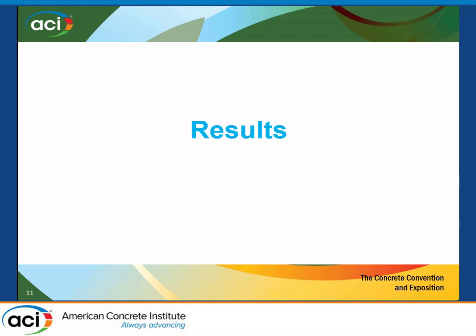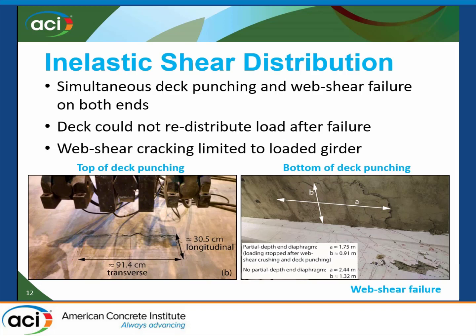So some results. The failure mode was interesting. It's been reported in the literature, so there is a paper behind this in the SP that I mentioned, and there is some background and literature review that I didn't want to present today. But this failure mode isn't uncommon. What happened was when we hit the right load, there was simultaneous deck punching above the interior girder, but also a web shear failure in the beam.